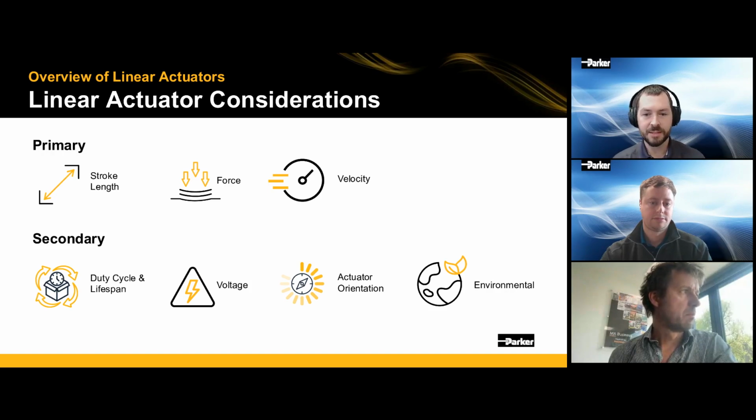First would be design cycle or duty cycle and lifespan. Understanding how the actuator is used is really critical. Is this actuator only going to be used once a day and sit long periods of time in between use? Is it going to be used frequently for maybe a couple hours and then sit maybe over a weekend?